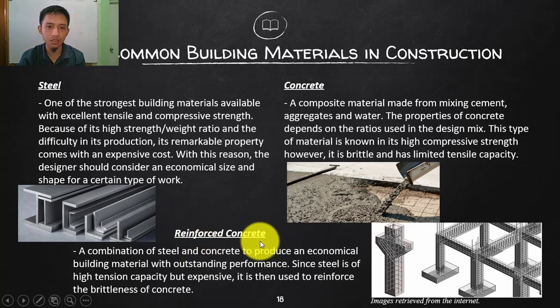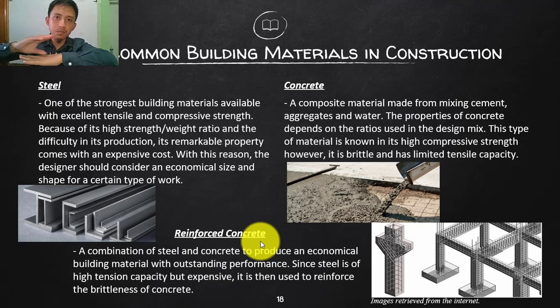Reinforced concrete. Most of the time, if tension is not common in a member, then we do not need to put steel. Just like on pavements, on roads. In roads, the scenario is that you have the pavement and the car is passing above. So those are mainly compression forces. If you look at the actual construction of pavements, there is no steel reinforcement, since again the tension is not that high in that type of member.